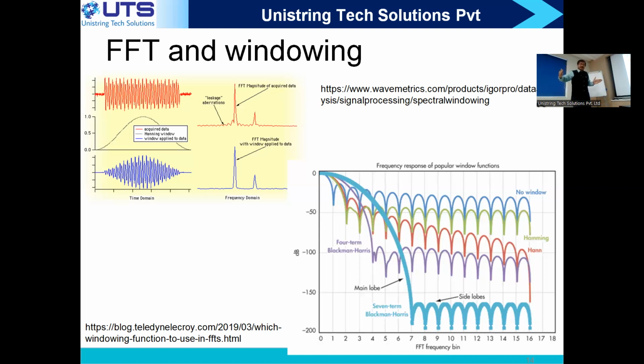Even that small chunk, you are cutting with a sharp cut, because all the remaining samples are zeros. From here, I have samples. Now, this becomes a challenge. This is your rectangular windowing. So what we would like to do, instead of cutting that, is apply some windowing functions.